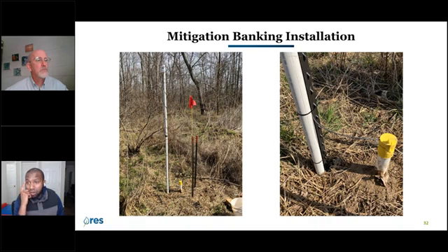So one question is around the hopping mechanism and the distance. RF is a bit funky. I like to say no two systems will operate the exact same way, based on the environment they are in. But a conservative way we spec this product is that the hop from one device to another is about 1,500 feet or about 600 meters, but it does require some level of line of sight.